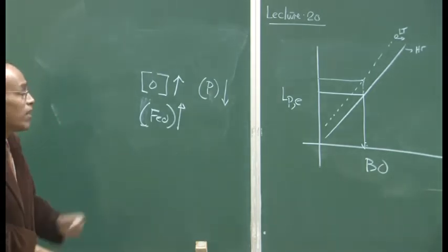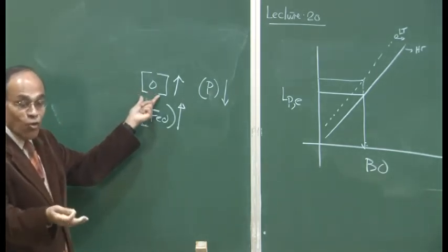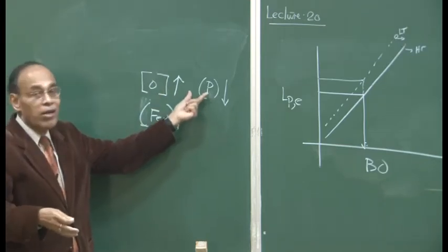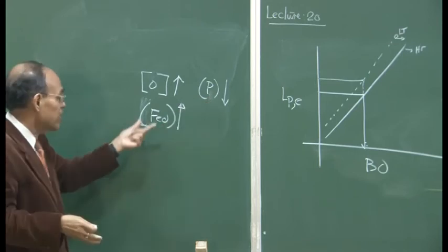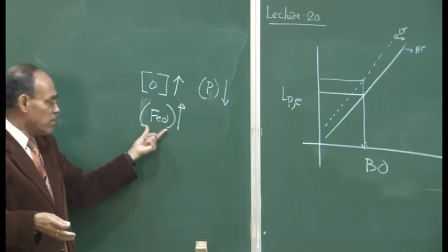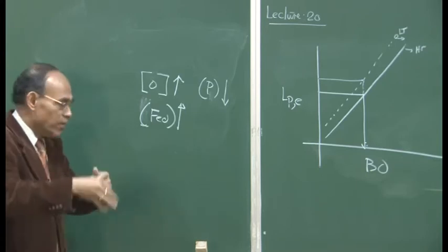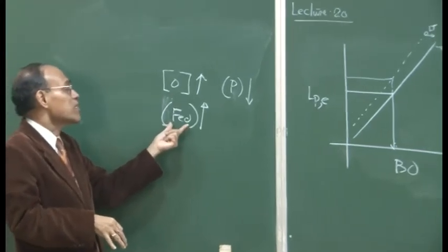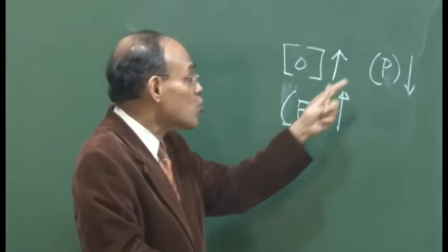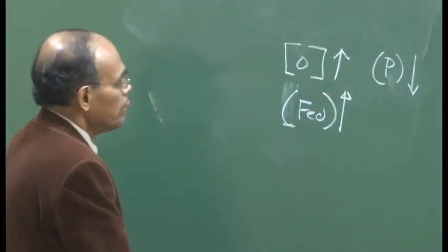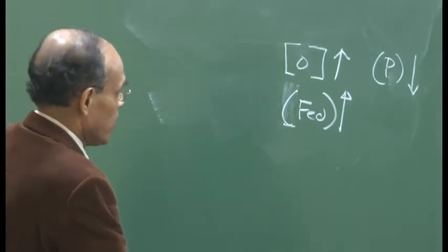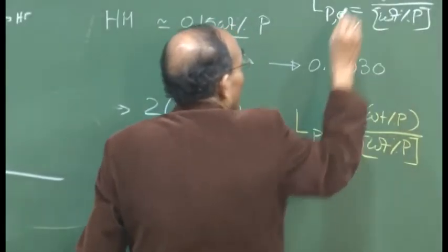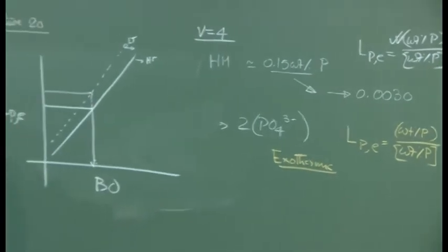Okay? So, as the oxygen content of the melt increases, you can get good phosphorus removal, or a large equilibrium partition coefficient. Alternatively, I can say, in one and the same statement said in a different way, if the slag oxygen potential is higher and the slag contains a large amount of FeO, in that case also you can get a good value of LP, quite a high value of phosphorus in the slag itself.